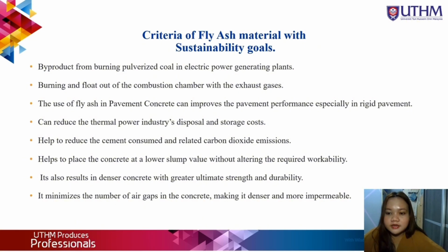Other than that, it helps place the concrete at a lower slump value without altering the required workability. It also results in denser concrete with greater ultimate strength and durability. And it minimizes the number of air gaps in the concrete, making it denser and more impermeable.